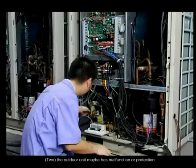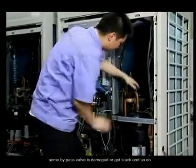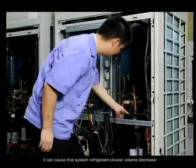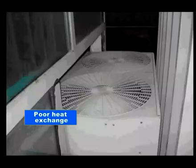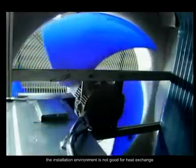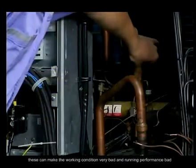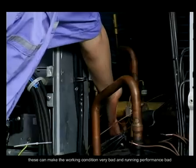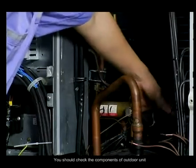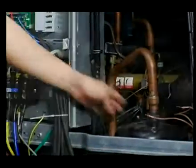2. The outdoor unit may have a malfunction or protection. Some bypass valve is damaged or stuck and so on. It can cause the system refrigerant circulation volume to decrease. Outdoor unit air return is short circuited or the installation environment is not good for heat exchange. Outdoor fan air volume is small. These can make the working condition very bad and running performance bad. You should check the components of the outdoor unit and judge if their action is normal when the system is running.